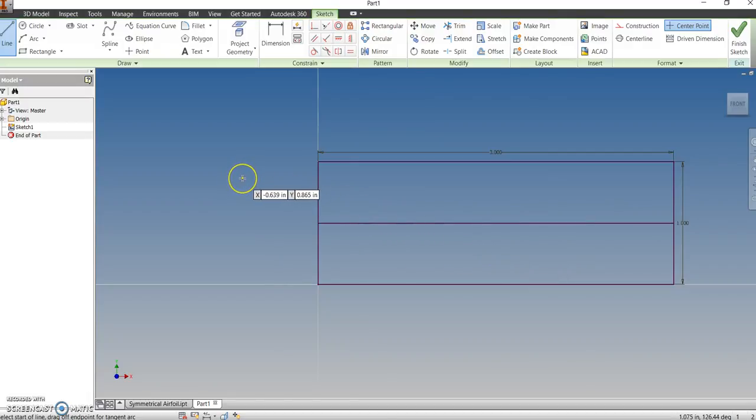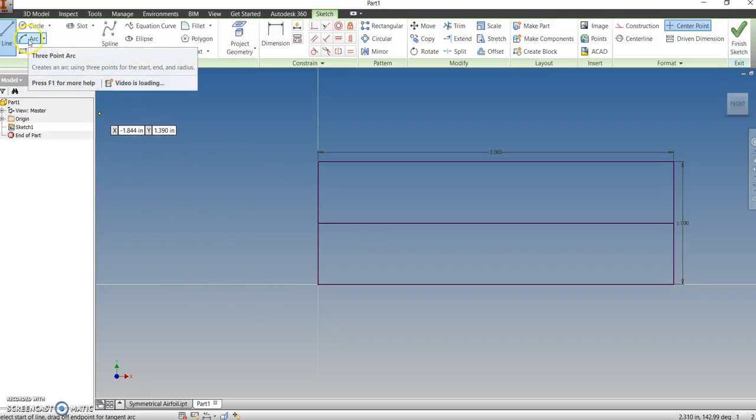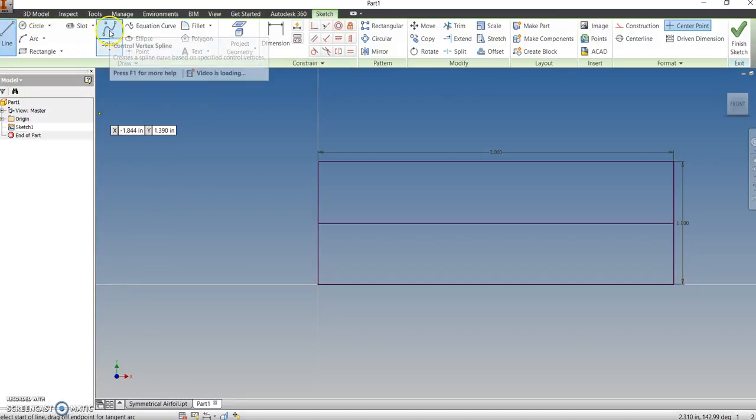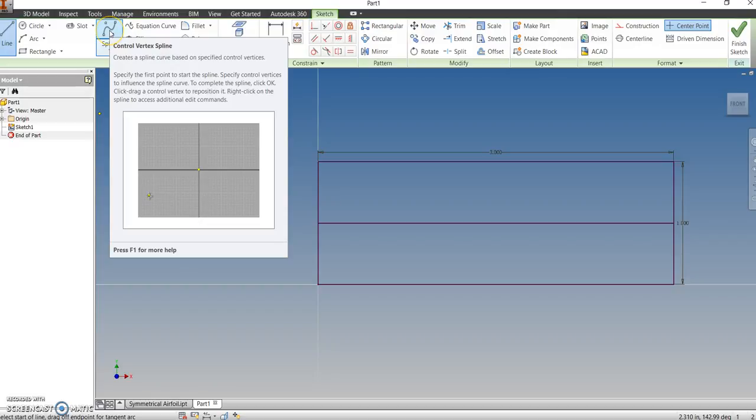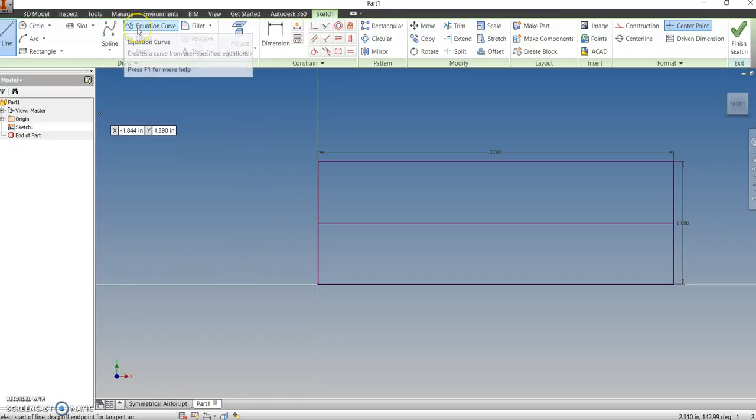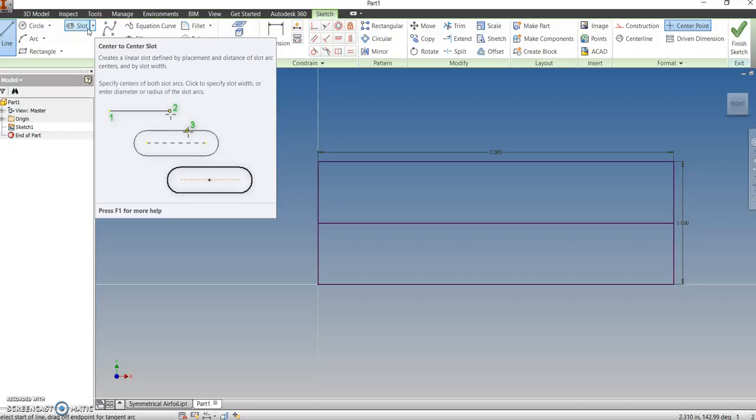And then I'm going to look at my design, all right? This is really where you have to look at your thumbnail sketches and now incorporate them onto the computer screen. A couple of tools you're going to want to get familiar with are the arc tool here, and you might use the circle tool and the spline tool. The spline is a great tool when we actually make the unsymmetrical airfoil. It's like a freeform drawing tool. Anytime you're wondering what a tool does, if you just drag your cursor over that tool, it will give you a preview of what the tool does.